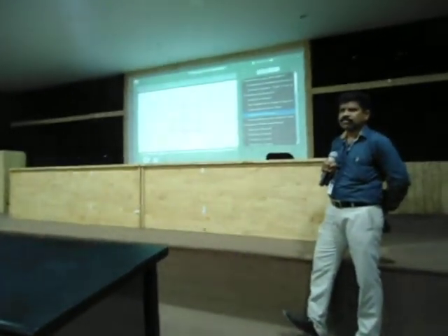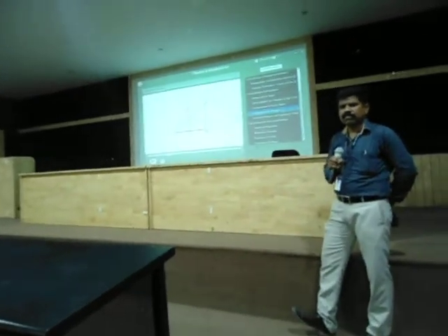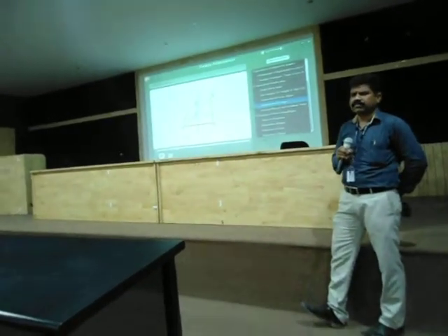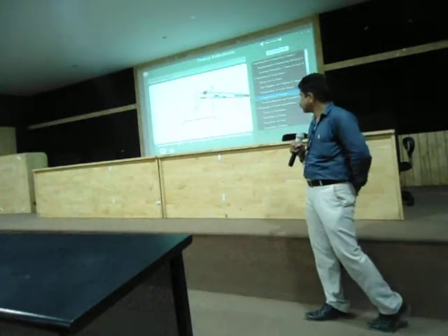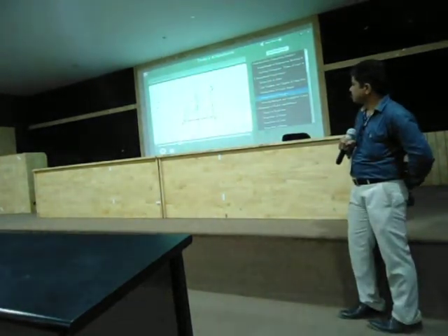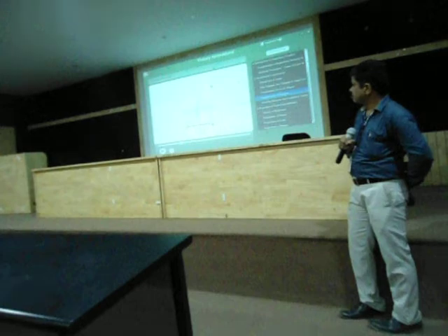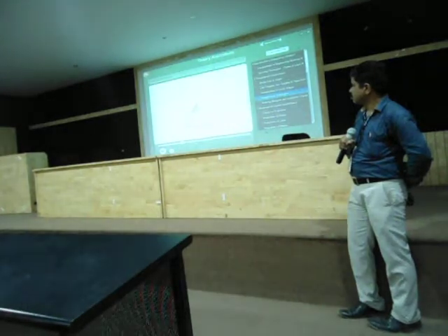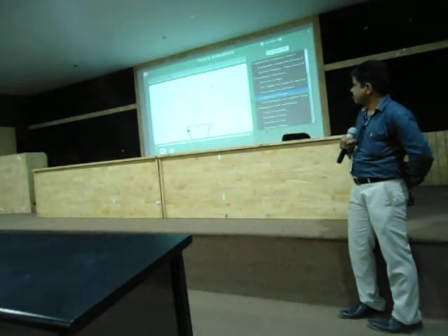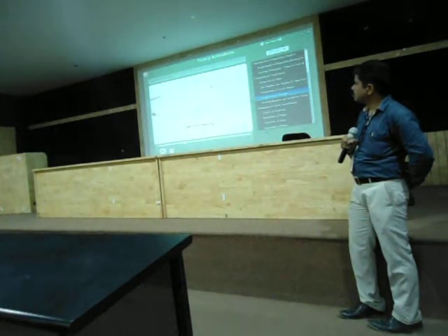After that, bisect the line 4 to 6 at point 5. Measure the distance of line 5 and transfer it above to obtain point 7. Draw a circle using point 7 as a center and radius of E7. Using a compass, make 7 equal parts of the circle with side length as AB. So here is our heptagon.